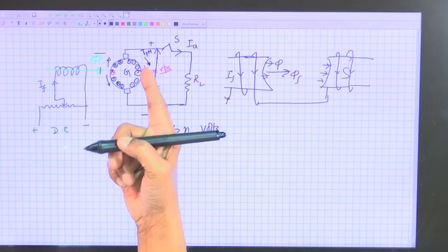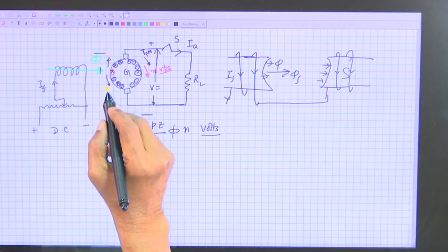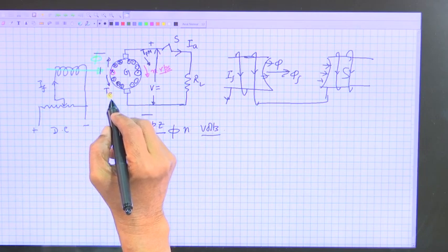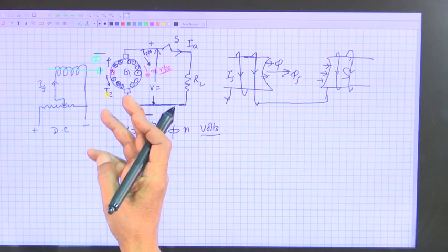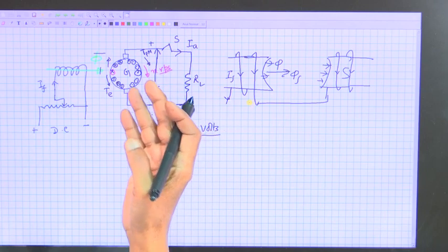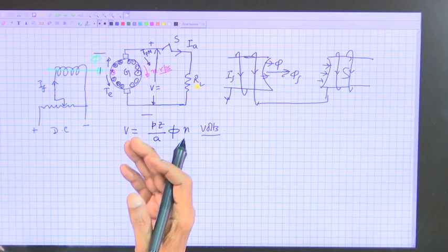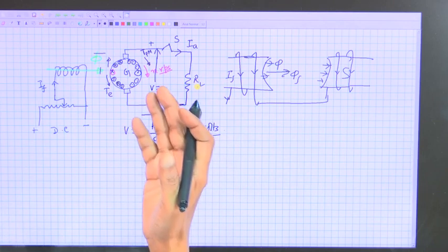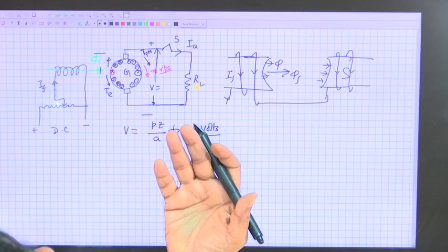The prime mover torque is a mechanical thing; who is providing the opposing torque is the electromagnetic torque. And if you find the generator is supplying power running at a constant RPM or RPS, you will conclude the prime mover torque and electromagnetic torque are the same.